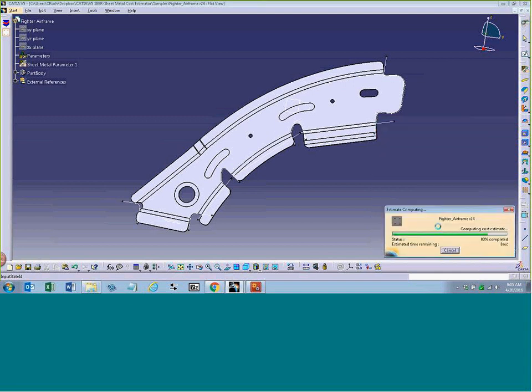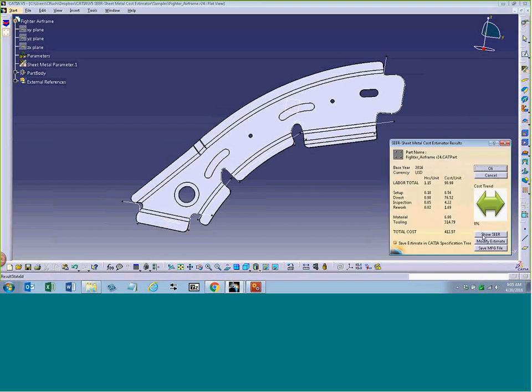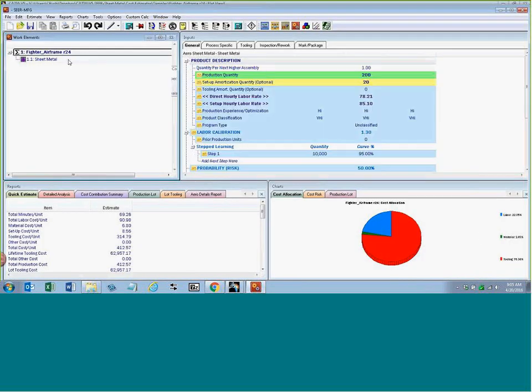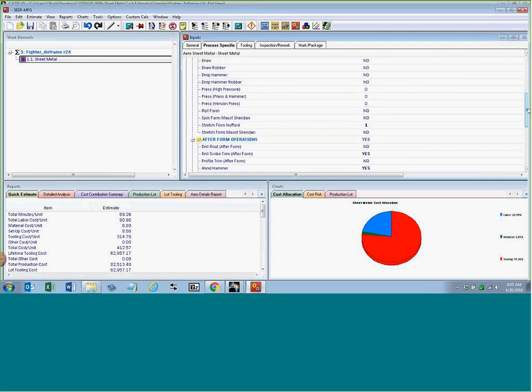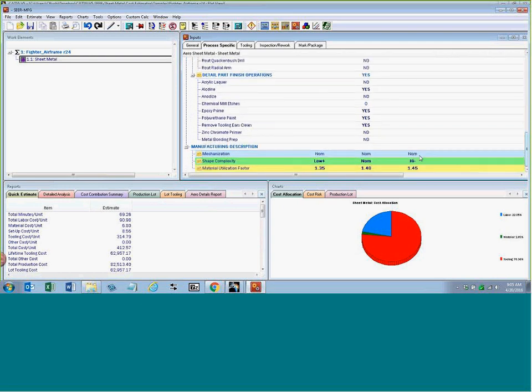Yeah. So we also could make a rule. You certainly could make a rule that says anything you select stretch form, if your typical grip is 6 inches or whatever, you add 6 inches on either side of the length, or 12 inches total, and you would have that considered in the estimate for handling, etc., as the cost of the material and material utilization.